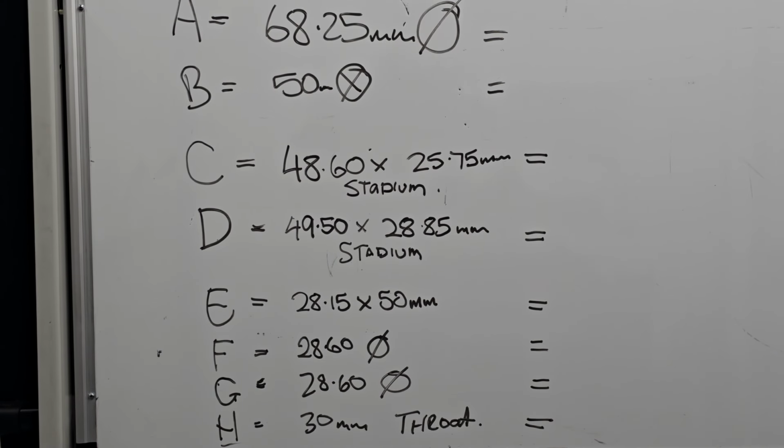So what we've done here is basically just labeled the induction from the bell A, B, C, D, E, F, G, H at the valve seat. And we've given ourselves rough measurements so that we can calculate the area, or the CSA, of the total induction system. So now we can see where our points of improvement need to be and our points of letdown or poor design. So we're going to map the intake and cylinder head.